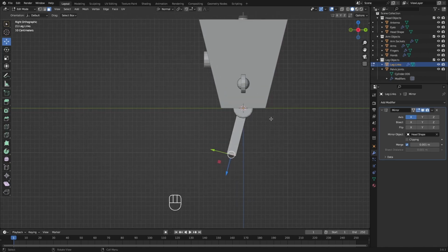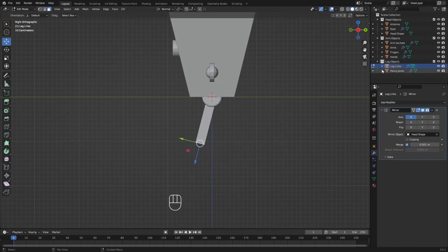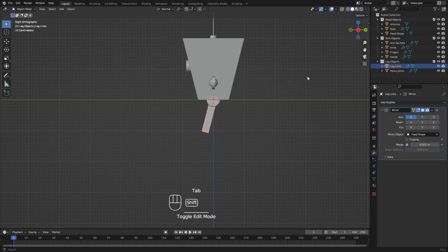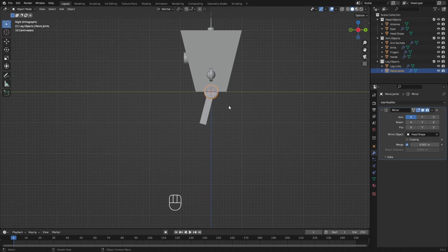And that's a way that we can use to copy modifiers. There are a bunch of other ways, but let's keep with this one for now. And all right, now let me close this one here, and I'm going to object mode again. Now, what I want to do is the knee joints. And to do the knee joints, I'm going to recycle the pelvis joints, just like we said before. So Shift D to duplicate, and then we can move it to where it should be.